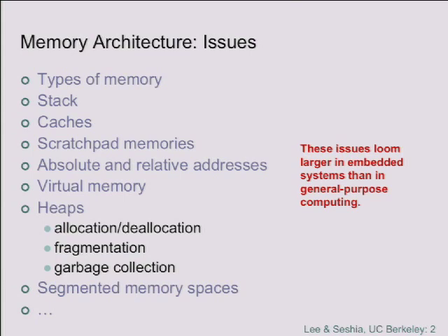How do you think you design a memory like that? What happens when you hit the 10,000 limit on, suppose you've been writing a lot to a certain set of locations? Well, hopefully your memory controller will detect that and will reallocate to another set of cells. The controller becomes rather complicated then, okay? But eventually, the capacity of the memory is going to start decreasing because you don't have enough cells, right? You've exhausted them. So you don't want to be using flash to do a lot of updates. So that's another issue that you have to be aware of.